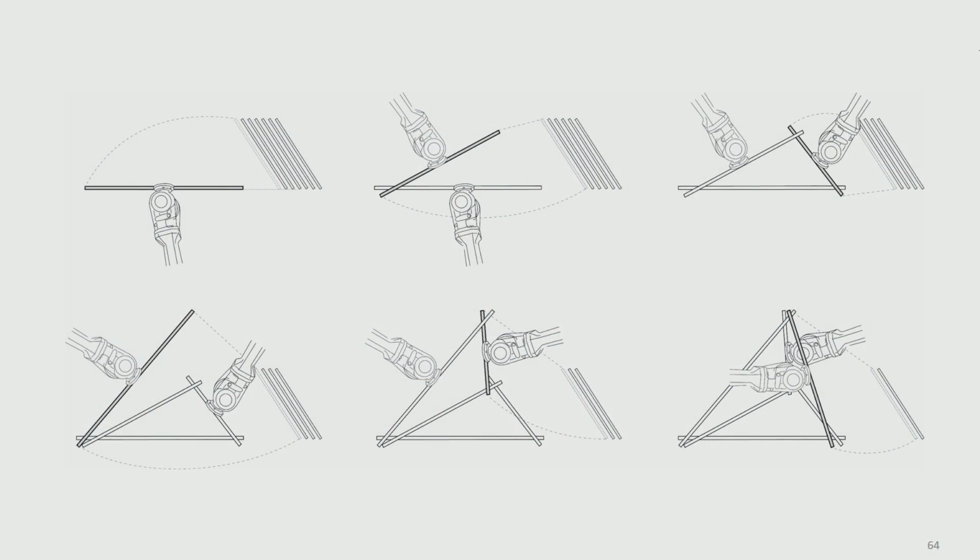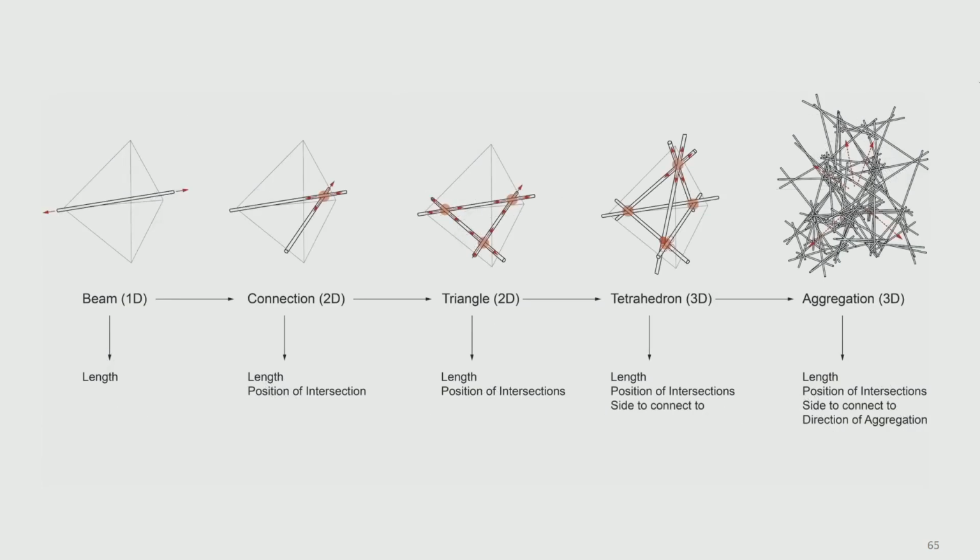You have one robot that brings one element, and you have the second one bringing the second element. And once the connection is done, in this case we did it by hand manually, one of the robots can let go again and bring a new element, but the other robot stays connected to the structure. And this process is repeated over and over again until a stable configuration is found. So what happens is that one robot is always attached to the structure, and it can serve as support for the structure during the build-up and also as a geometric guide, so you avoid deformations and large tolerances.